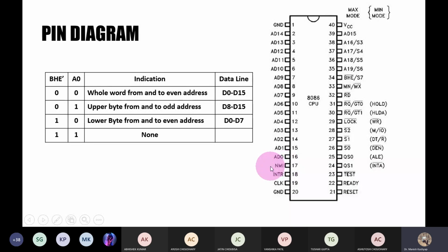In 8085 we had the TRAP instruction, which was non-maskable. In place of that, you have an NMI pin here, which is a non-maskable interrupt, and INTR, which is a maskable interrupt. So these two pins are there, and you can use them for making external interrupts to 8086, right? And we will see how these interrupts are acknowledged in minimum and maximum mode when we see the INTA bar pin, etc., in combination with these pins. Only two pins are present for this hardware, right?